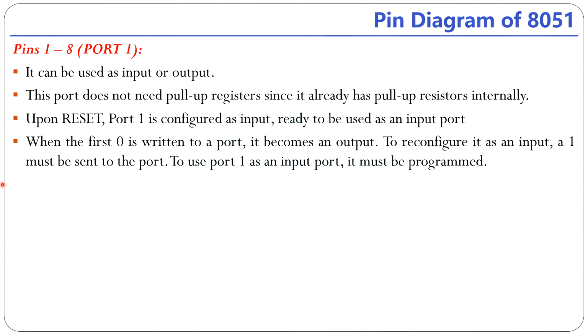Next, when a 0 is written to a port, it becomes an output. So to reconfigure it as an input, a 1 must be sent to the port. To use port 1 as an input port, it must be programmed. Next, pin number 9, the reset pin.